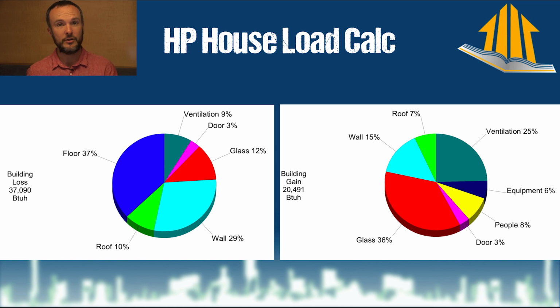So here's the way that my component loads work. I've got floor, which is my slab. That's bleeding some. I have 2 inches of insulation under there. I didn't want to add more than that because of the cost benefit, again, at this point, I've got a 1.5 ton split system air conditioner. They don't make smaller than a 1.5 ton in a ducted system.